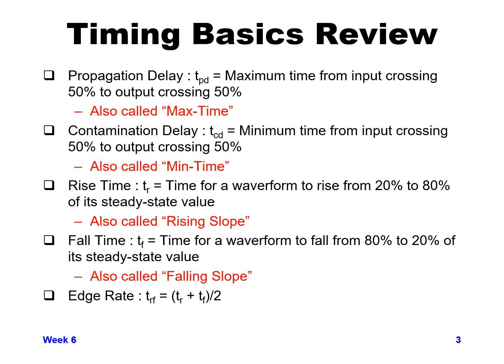For fall time, it's kind of the opposite of rise time. It's the time for the waveform to fall. So if it's starting at VCC, when it hits 80% of VCC on its way down, you measure the amount of time to get from 80% to 20% of its steady state value down to ground, and that will be called the fall time. Again, at Intel a lot of times we'll call it slope, and in the case of fall time it will be the falling slope.